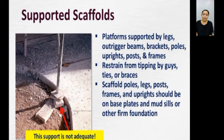Supported scaffolds. Platforms supported by legs, outrigger beams, brackets, poles, upright posts, and frames. Restraints from tipping by guys, ties, or braces. Scaffold poles, legs, post frames, and uprights should be on base plates and mud sills or other firm foundation.